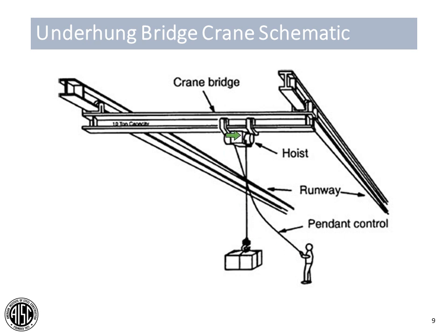That pendant will operate a hoist and trolley assembly, which is up within the roof framing system typically of a structure. This hoist and trolley travels back and forth along a crane bridge or bridge girder and hoists the load that is being moved throughout a structure. The crane bridge or the bridge girder is typically supplied by the crane manufacturer and has end trucks, which are these wheeled assemblies on either end of the bridge girder. Those end trucks travel on the primary items that we're going to be talking about today, which will be your runway beams or girders.